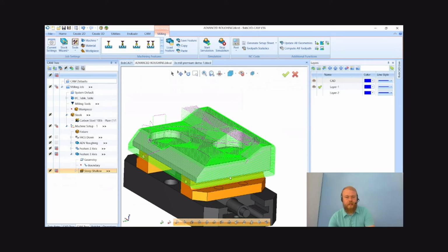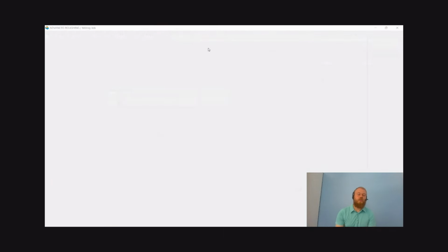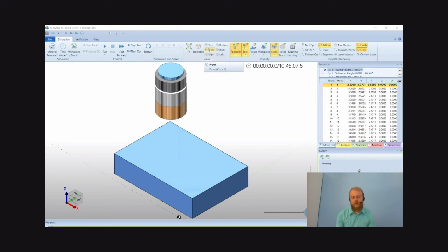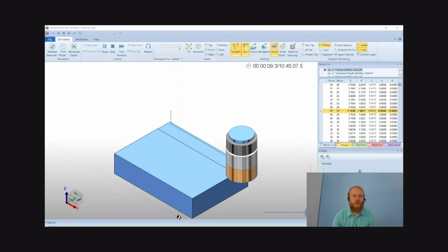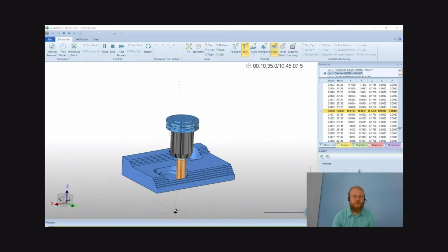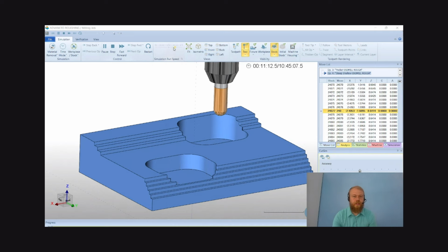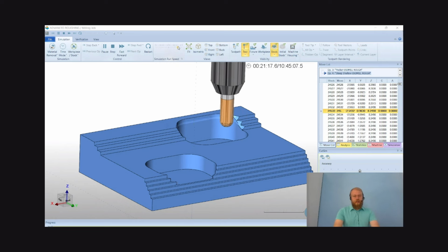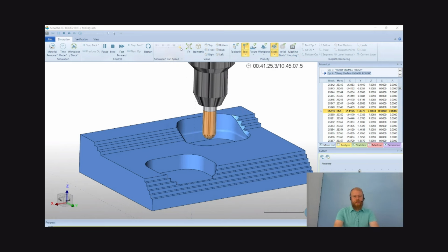So that's our steep shallow toolpath going all the way down to the sides there. And we can take a look, if I turn it on here, at it in our simulation. That's a great toolpath. Again, it's sort of 2-in-1. You've got a Z-level finish operation for any tapered walls, and for any vertical walls or flat horizontal areas, you have either a planar or an equidistant toolpath to follow along the 3D model that you have here. So here's our last Z-level finish, and then the steep shallow toolpath.